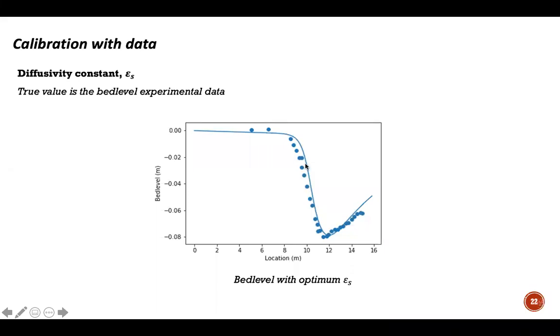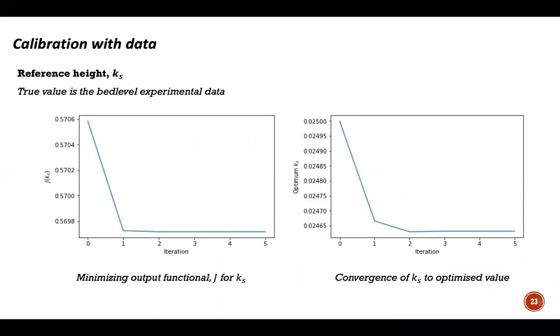I think it might be because there's too much sediment entering. Like I said before, input sediment is a big uncertainty, so I'd like to calibrate for that. But we can also look at calibration for other parameters which might improve it. So this is for the friction.